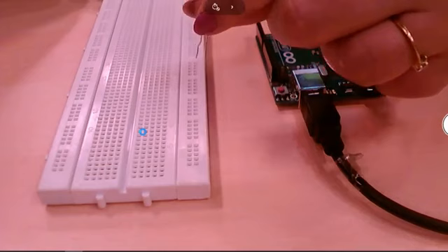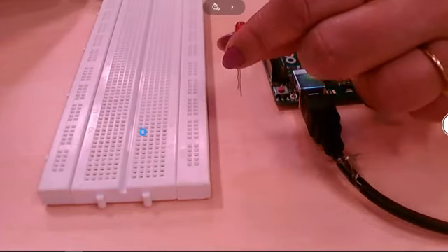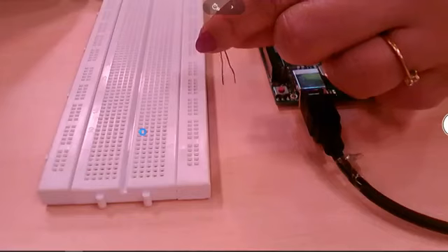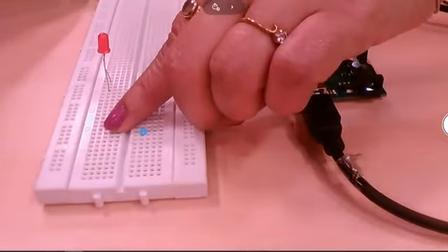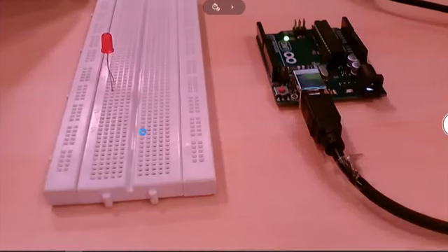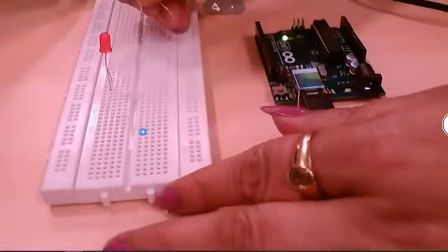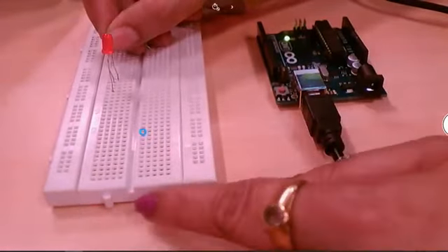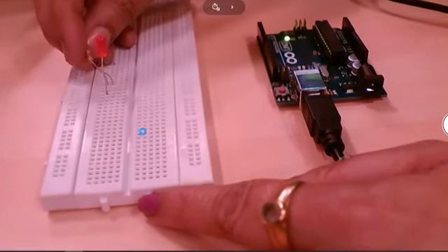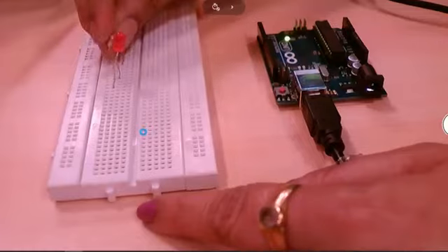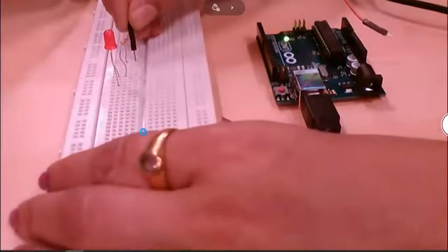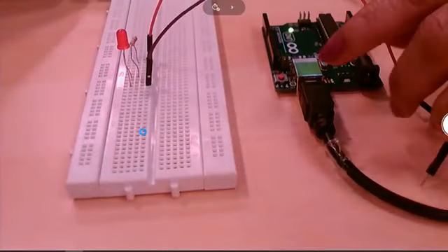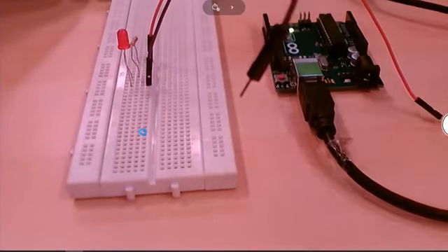As we already discussed, there are two legs to the LED. The longer one is anode and the shorter one is cathode. Horizontal pins on your breadboard are not connected, but the vertical holes are connected. So to one end of the leg, I will take the resistor in connection as series, and the other leg again I will put in the same horizontal line. You can see that in detail. The basic connection I have kept ready.